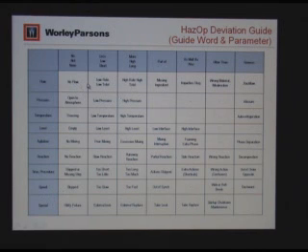Such as no flow or low flow, and high flow or high pressure, and those are all kind of deviations from design intent, like tube leak, utility failure, maintenance, during maintenance, and agitation, all that.